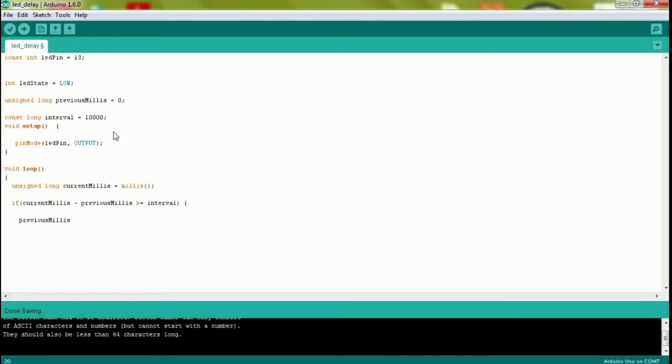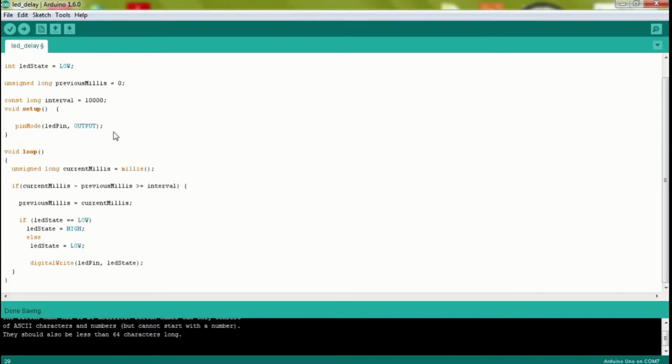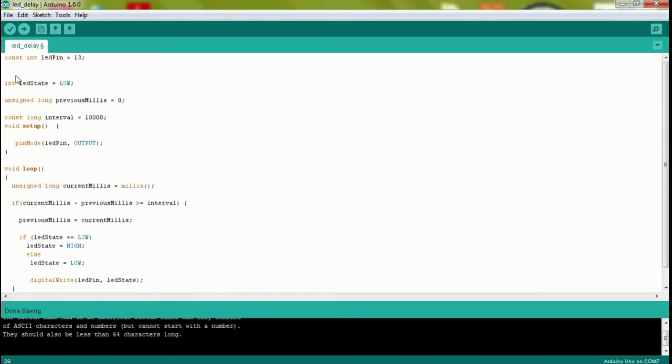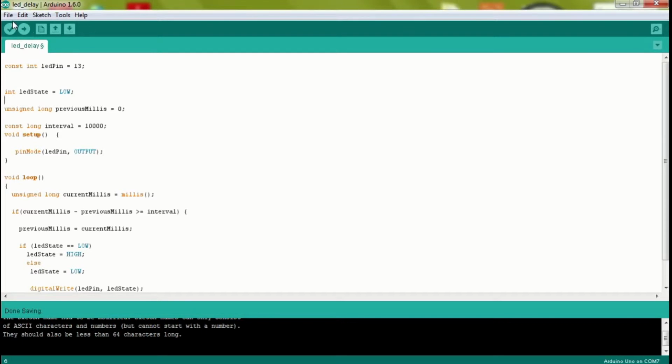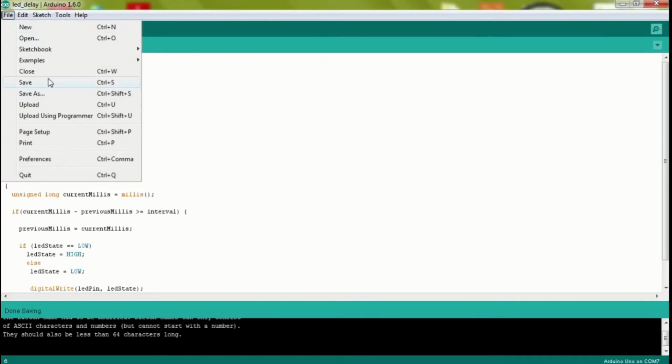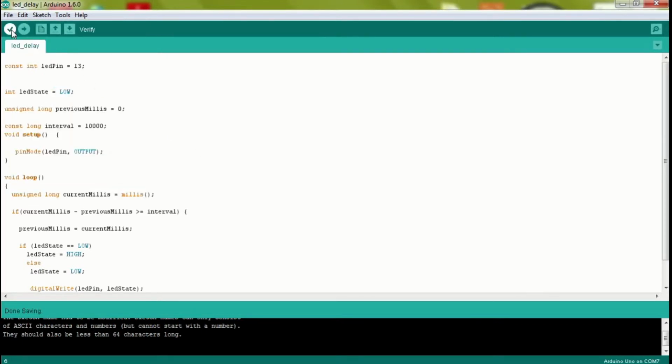To do this, we use a command named digital write. We will use a delay which is programmed by milliseconds, so we'll insert 1000 milliseconds, which is equivalent to 1 second. This is only valid until the next command is due. Void loop causes the Arduino program to go into a literal loop, hence its name. After you're certain of your Arduino coding, connect your laptop or your desktop computer to your Arduino using a USB cord, as shown next.